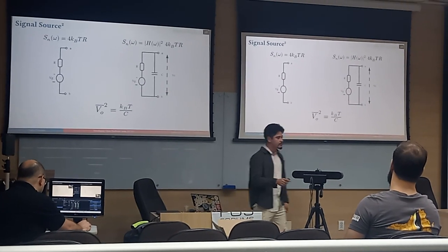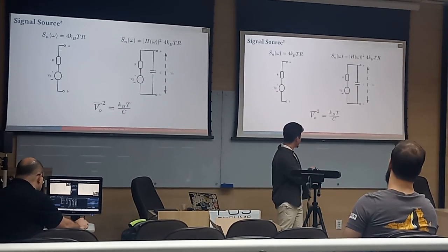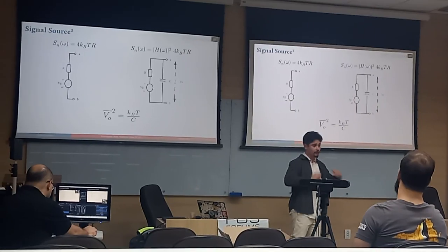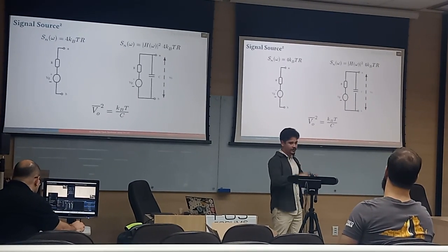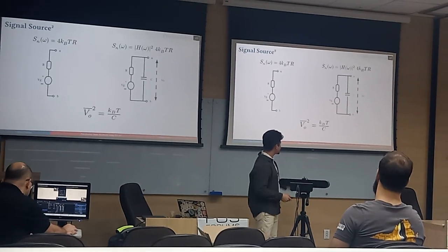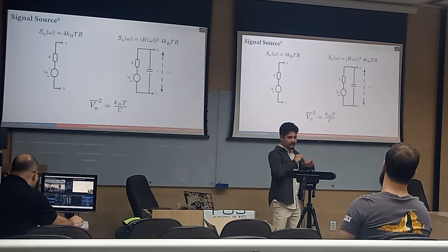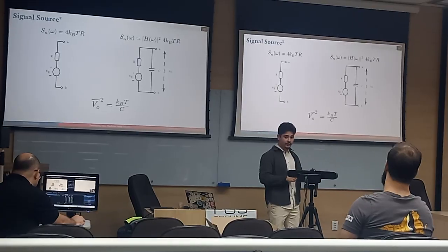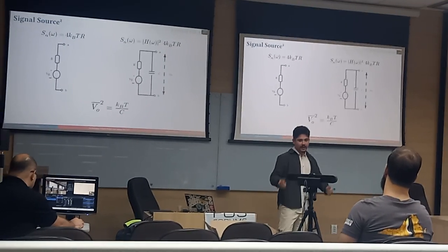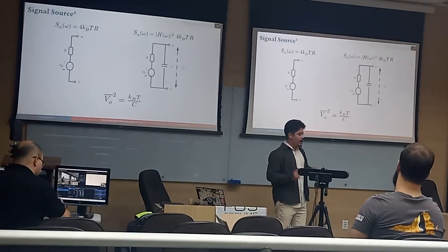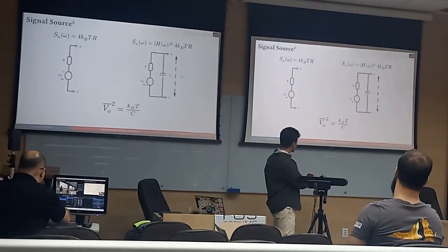It is a bigger value, because using a small capacitor you can increase this to nanovolts, way better. Not yet where you can measure it with a multimeter, but way better. And we get rid of the dependency on the frequency and the resistance. So very good. A capacitor is way better behaved than the resistor. So this is the main point.